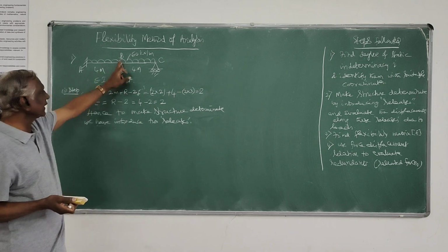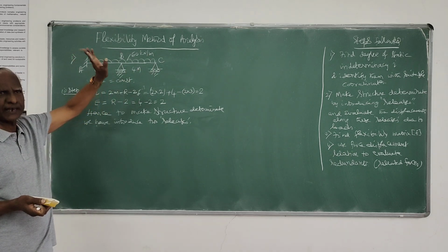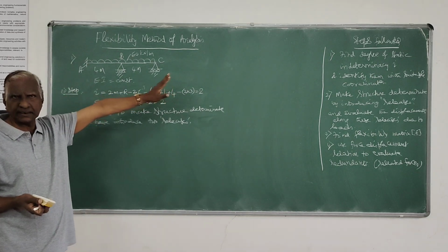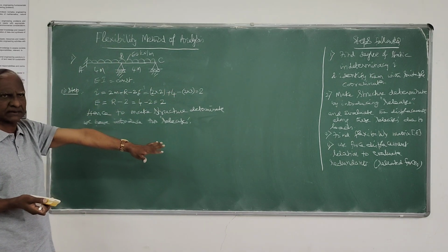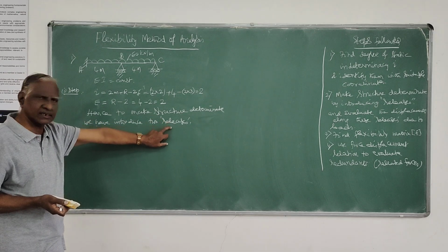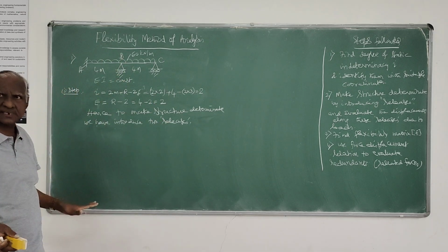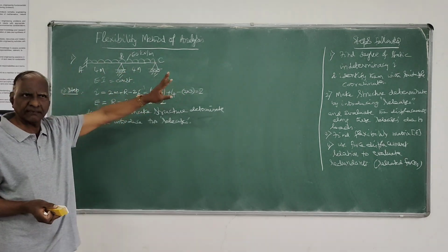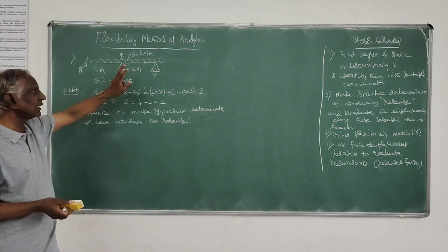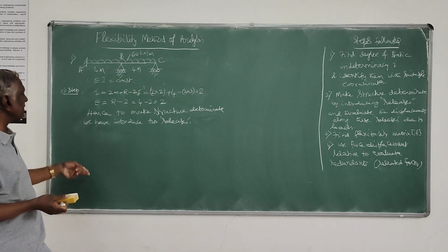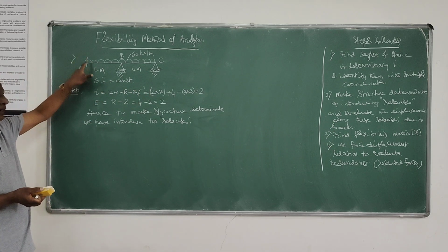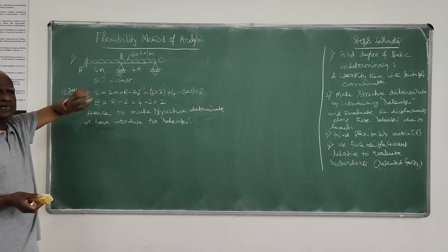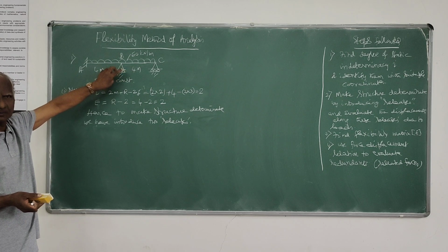One is we can remove these 2 support reactions at B and C. If I remove them, it becomes a cantilever, so it becomes a stable structure. While introducing the releases, the structure should be stable. That you have to make sure. Second possibility is you can remove the moment here, so make it a hinged end, and you can remove the mid support here.